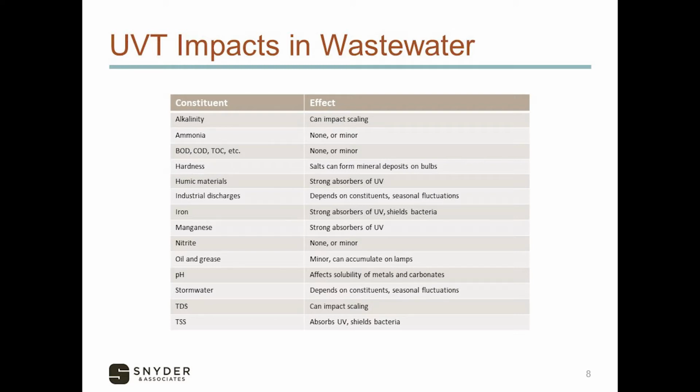Humic materials are very strong absorbers of UV radiation. And guess what? A lot of wastewater has high humic material content. The other one that's a big deal is hardness. Now, I know nobody in the Midwest particularly has hard water, but remember, even though that water's been through the water treatment plant on the drinking water end, probably the filter backwash and other things have found their way to the wastewater end.